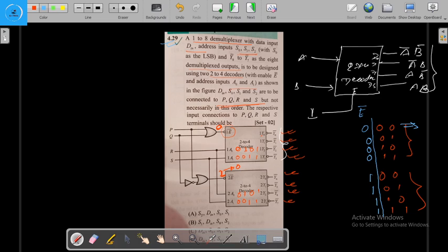And when we make this signal, let me consider this signal as a z, since p is given here. So for z equal to 0, the first decoder is working. For z equal to 1, the second decoder is working. So if z equal to 0, this first decoder will be working, and for 0 0 we get Y0 bar, for 0 1 Y1 bar, for 1 0 Y2 bar, and for 1 1 Y3 bar. Similarly, if z is 1, z is present here, this we have considered as z, and z bar will be present here.